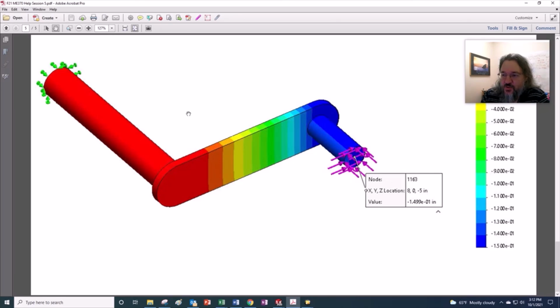The reason you might do that is if you're trying to prove your simulation software is appropriate for the application, you do it for a simple thing that you could actually measure, and then you might extend it to a more complicated thing where you can't actually build it and measure it, but you can do a simulation. That's the method of validation. It's really an important part of being an analyst or using analysis software.